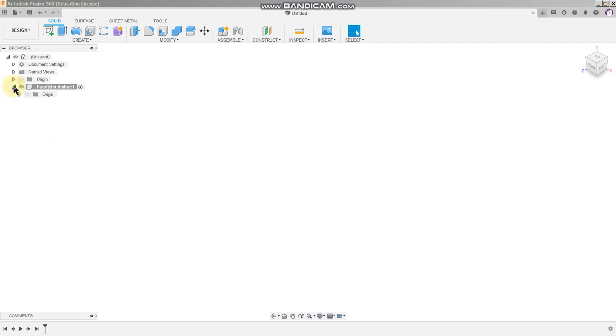Now, every component carries with it its own geometry. The origin point, you can see it coming up in the middle of the screen. I'll do that again. The origin point, the x-axis, the y-axis, the z-axis, and then three planes, xy, that's a very faint grey in the middle of my screen, the xz, and the yz.